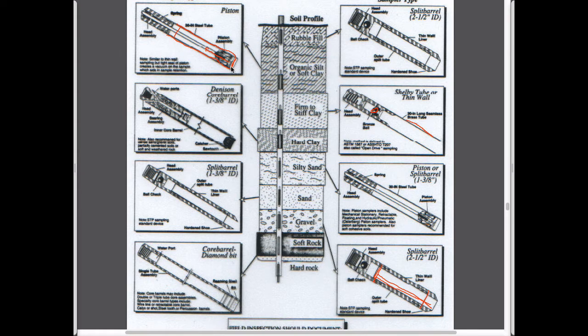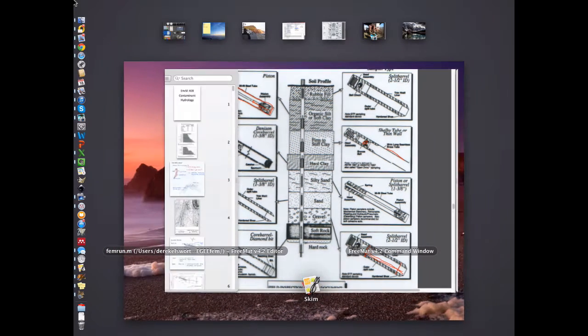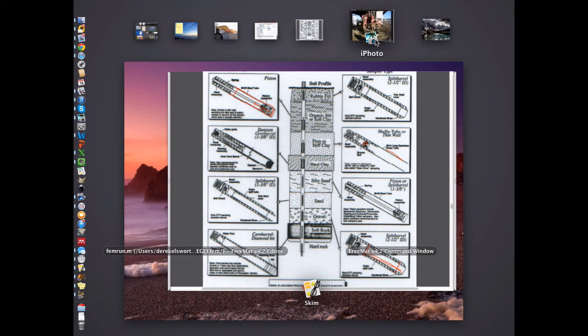So the two main kinds. Soils such as sands and gravels, thick wall cylinder. Soils such as silts and clays, use a thin wall cylinder. Undisturbed samples, useful in the lab. Highly disturbed samples, less useful. And of course you can use core diamond drilling in these things as well. And so did we have some pictures of these?